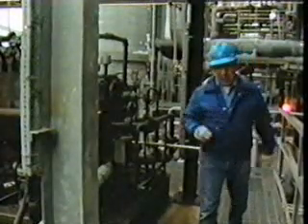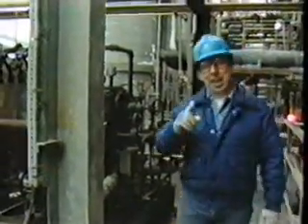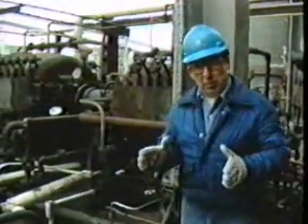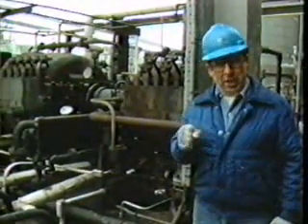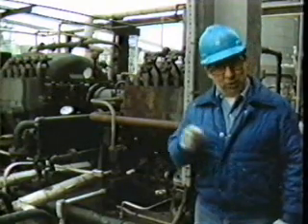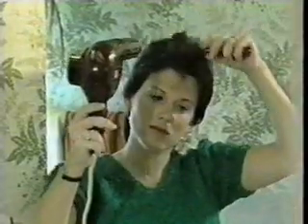Commonly, you'll find two main types of compressors in use today, the dynamic and positive displacement. Now, the most common positive displacement compressor is the reciprocating compressor, and the most common dynamic compressor is the centrifugal compressor. Every day, someone around us uses some kind of centrifugal compressor right in their own home. This hairdryer, for instance, is a type of centrifugal compressor with a heater. Even this vacuum cleaner is a type of centrifugal compressor.